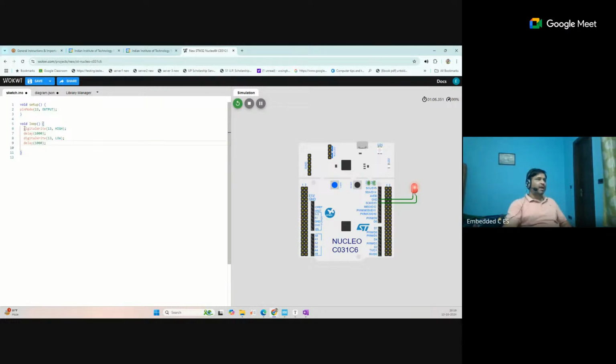So you can see this will be turned on first, then delay for 1 second. After that, this operation will be performed, then it will become low, then 1 second delay. After that, again, this first line will be executed. So in this way, this will blink actually. Okay, so let's run again.